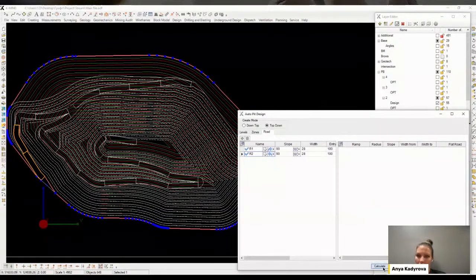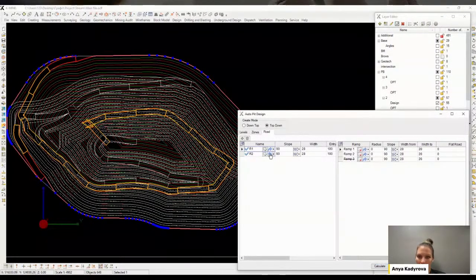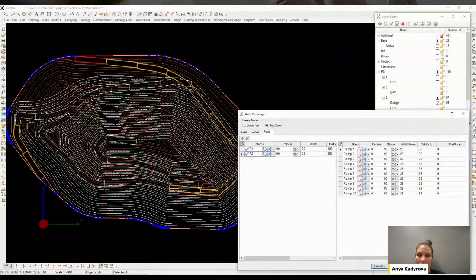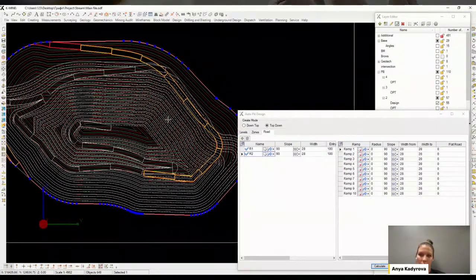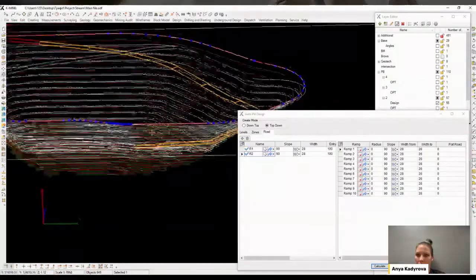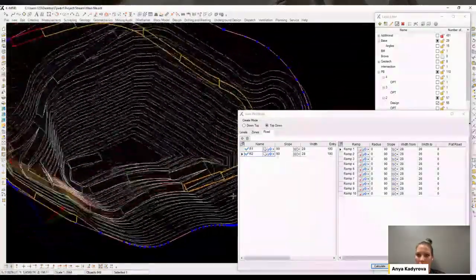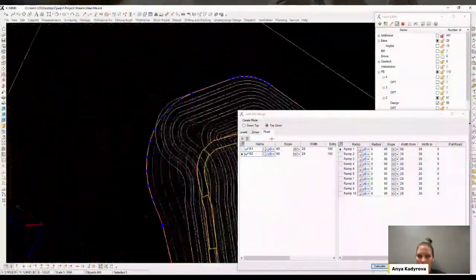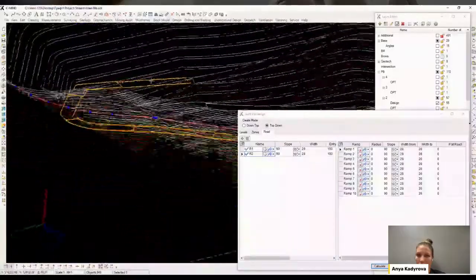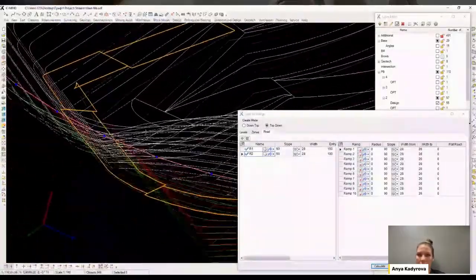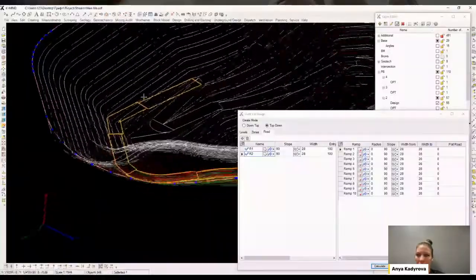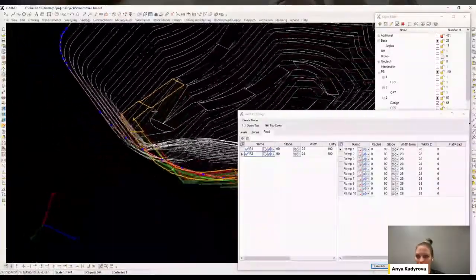Overall, in the process of building subsequent pushbacks, we can get ideas where the roads can be joined in order to leave them as much as possible for later use. If we want to do that, it's necessary to rebuild the previous pushback and leave the pillar in the right place, which is basically a section that will not be developed.